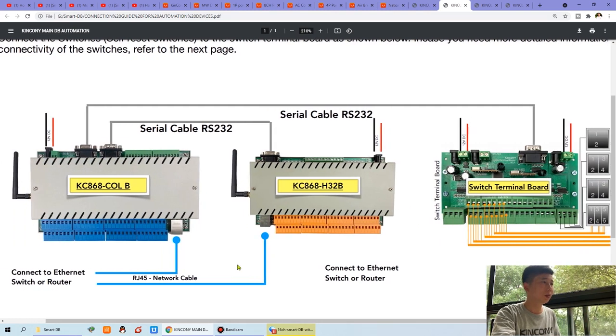And you can see this is the logic controller. The logic controller also uses RS232 to connect with the relay controller. So this is the second way for the relay controller. This is the automatic way. So you can set the input, track output, and the time, track output, and the schedule. When the time and date arrive, you can let the relay go on and off, and set the delay time. So this also has the network and Wi-Fi.